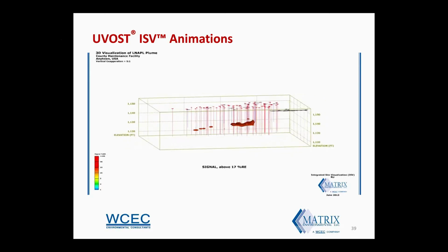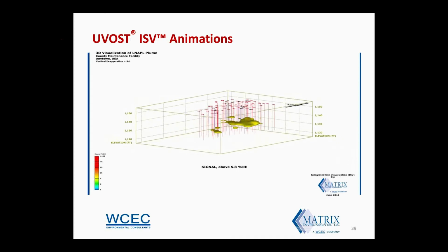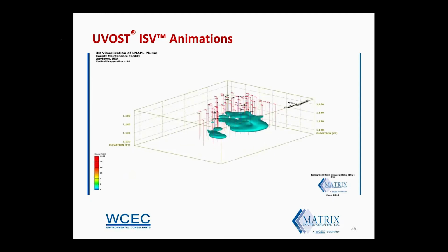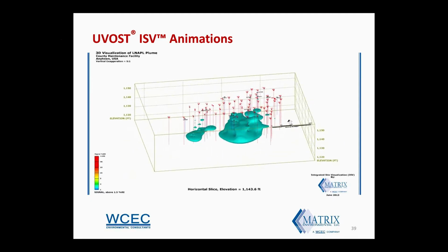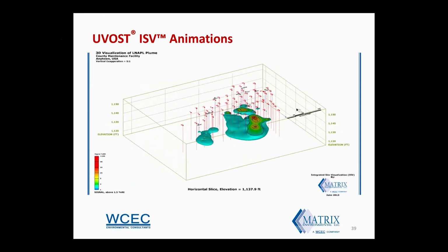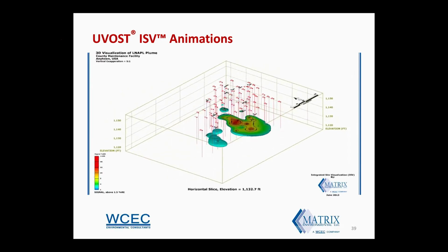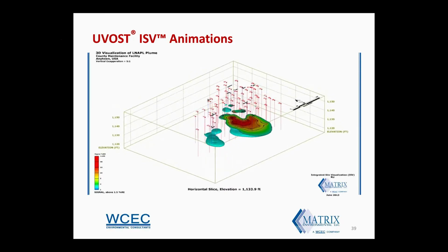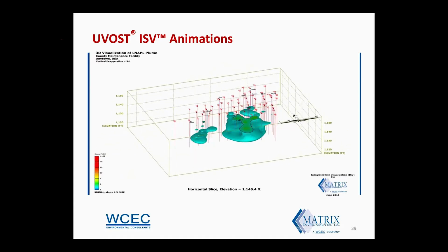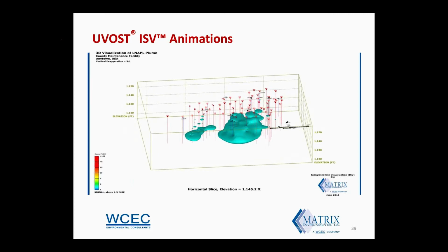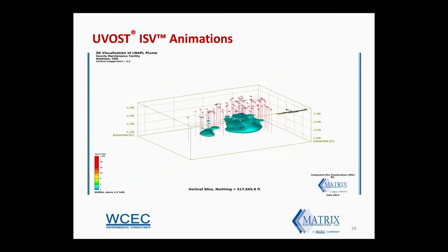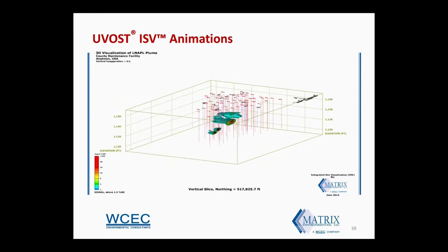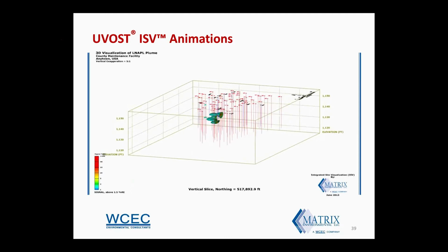plume shell. You can kind of see the areas of highest intensity back to lowest intensity, which is the extent of the plume. You can also see we've got all of our boreholes represented with what we call borehole tubes. This view is a slice that goes vertically, top to bottom and then bottom to top, to reveal the inner intensity at depth. So if this was an interactive 4D, you could pick the slice that you thought was valid, say at the soil groundwater interface, and see what the intensity of the inner plume was at that depth.